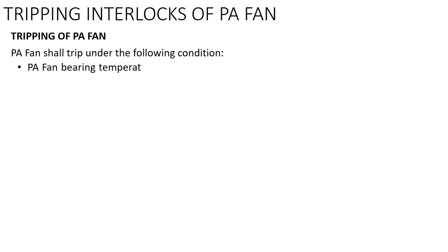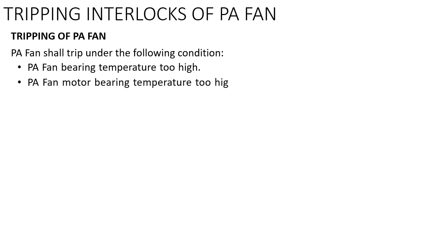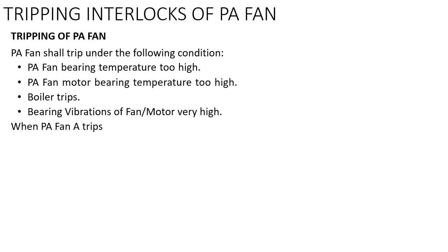Well, now the tripping interlocks of PA fan. The PA fan shall trip under the following conditions. Condition number 1 is PA fan bearing temperature very high. Then PA fan motor bearing temperature very high. On high there will be an alarm, on very high there will be tripping.